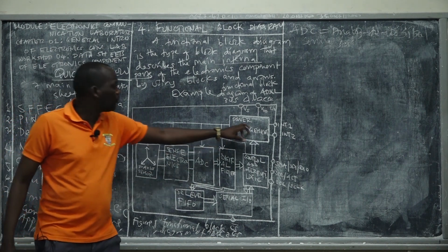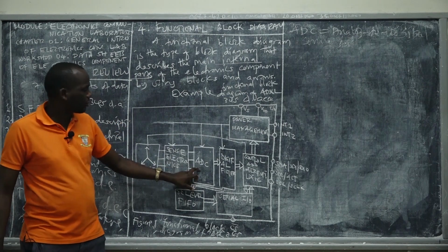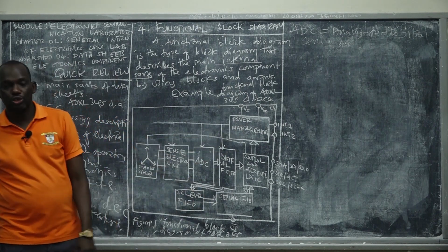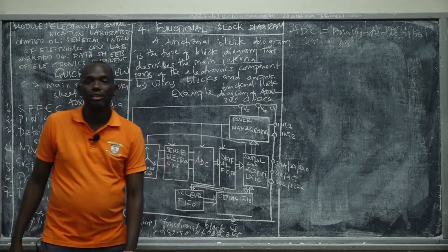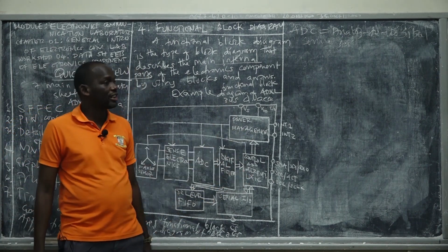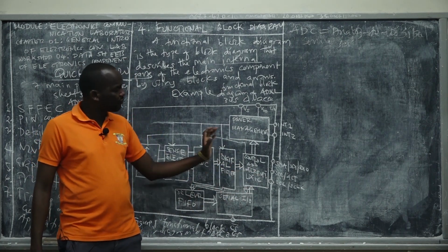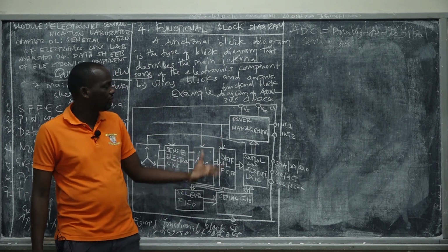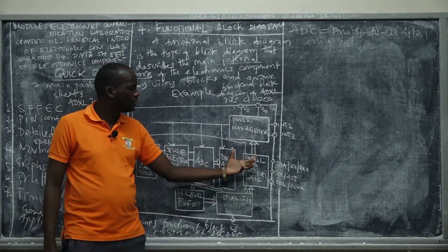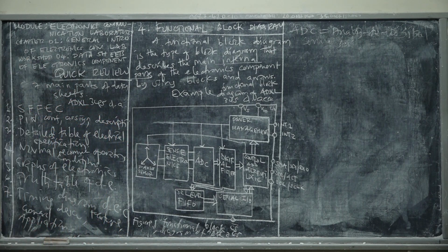Power management is just providing power, distributing power to all the different parts. But why do we call it power management? It means that this sensor is very sensitive to the power. Sometimes you can find digital accelerometer sensors which can receive 5 volts, but with this power management, what will be consumed here is 2 volts up to 3.6 volts, as we discussed in the features.